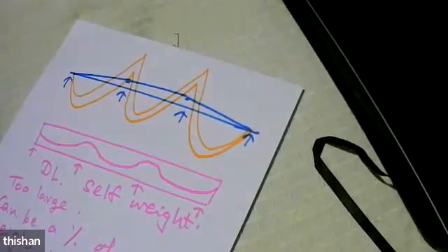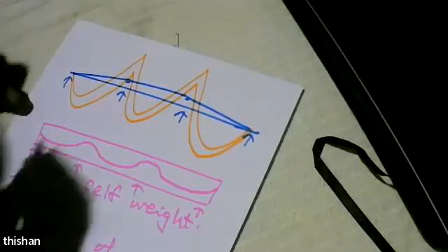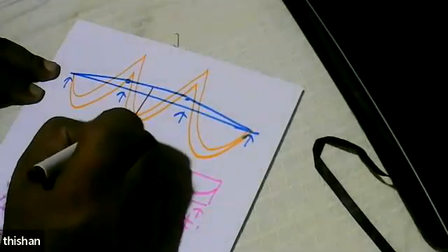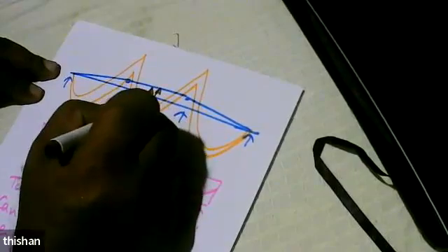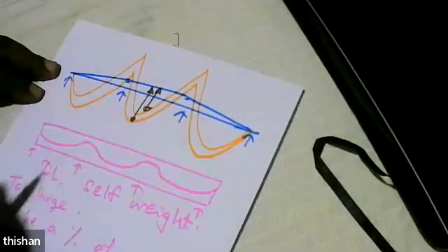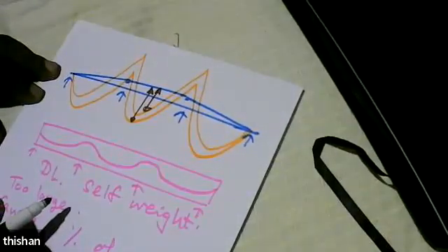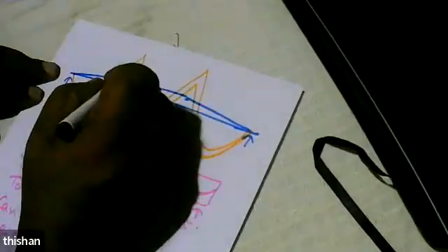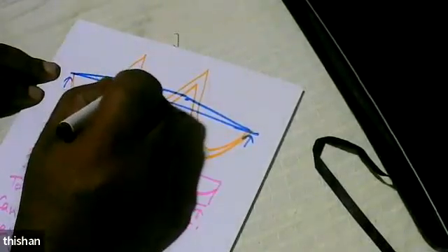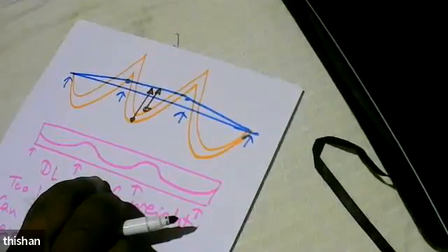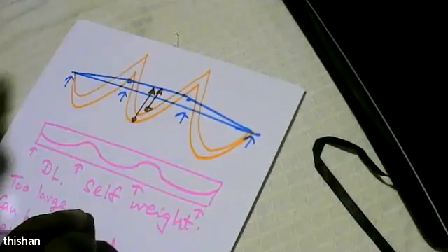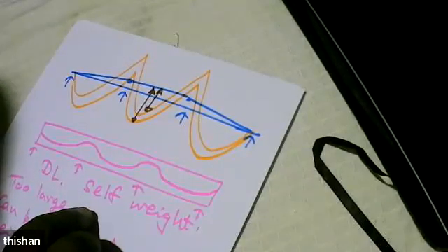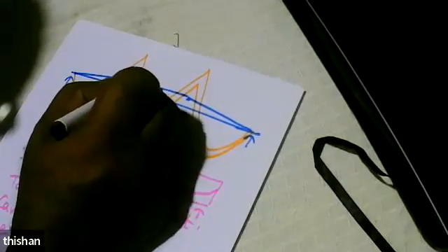Draw a new origin for the bending moment diagram, and then all the moments are measured from the new origin. So MA will increase, MB will increase. Here also MA increase means, MB increase means actually its magnitude becomes more. Right? Because it's negative, when you are reducing a negative value, it's increasing. But if you look at the magnitude only, what has happened to the magnitude? Reduced.